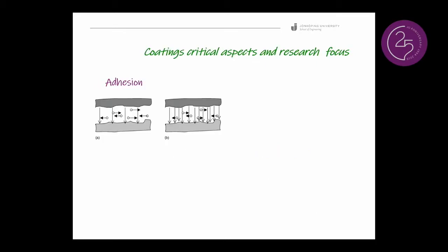And what is most critical in a surface treatment? If it is a coating, the most critical parameter is adhesion. If we add a material onto a bulk, we must assure that this material becomes part of the integrated system and attaches to the bulk material strongly. And therefore, we study the interaction forces between the new material on the surface and the bulk material.